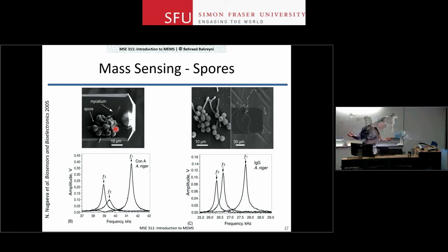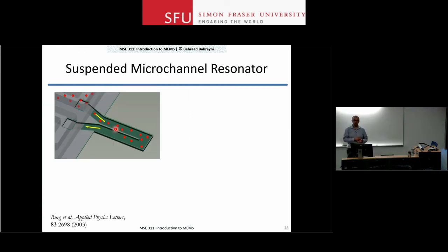And then people can be smart, and what they said in this situation was that, okay, let me do biosensing with these cantilevers. The problem here is that if you take one of these MEMS cantilevers and insert it into biosamples, which are usually in liquid form, the damping will be too high. The challenge is that the viscous damping inside the liquid is just so high that you cannot see your resonance. You will lose your resonance signal.